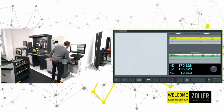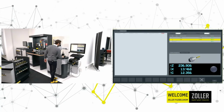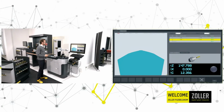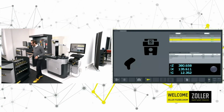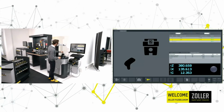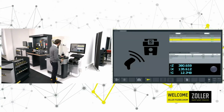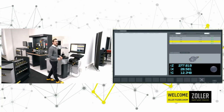So it's a user independent measurement in the fastest time possible, and as I explained already, user independent. So each user, even without training, measures the tools correctly. So you see me as an operator now here on the CNC presetter. All I have to do is clamp the tool, clean that tool, scan it, and hit the measure button. So how easy is that?